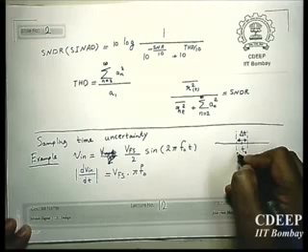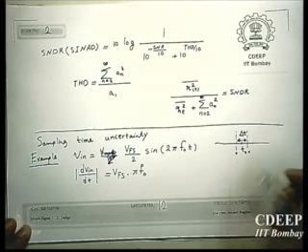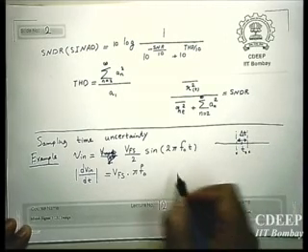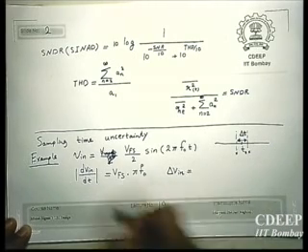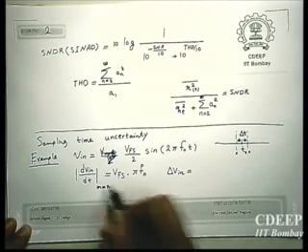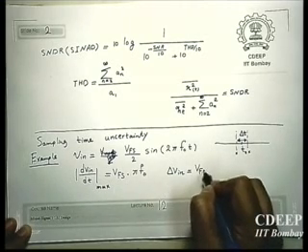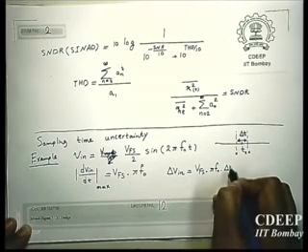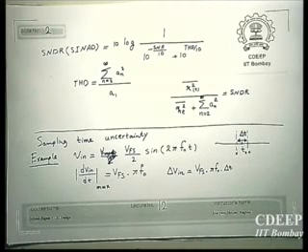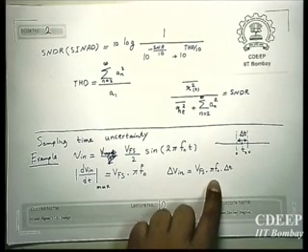You may sample it here, you may sample it here. Therefore, this delta t is not known. So we calculate delta Vin, the max value, which will be V full scale times pi F0 times delta t. This means that during this ambiguity interval, your Vin may change by at most this amount,